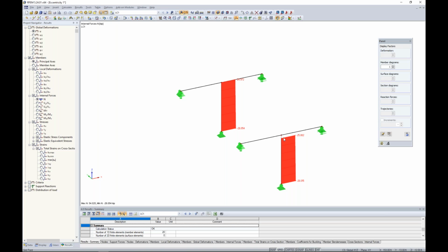So again, this isn't a BIM software. We're just truly here to do the analysis. Now the exception, well, we'll get into another exception in just a minute, but considering connection design, of course, with connection design, you need to consider offsets and eccentricities when a beam is framing into the face of a column. That's clear. But when we're looking at overall member design, in so many scenarios, it's just really not necessary.